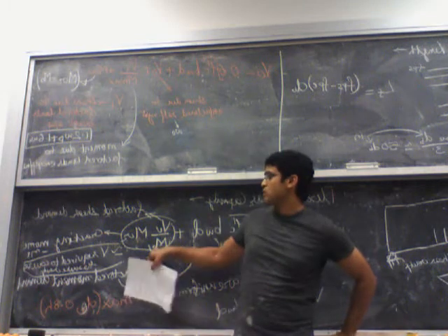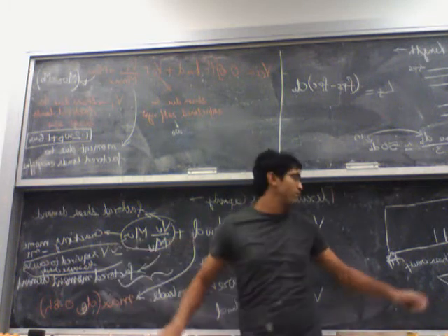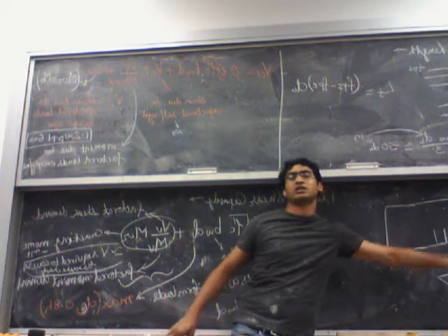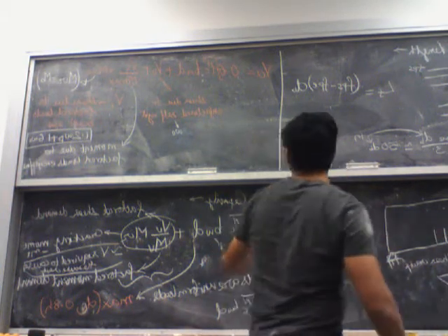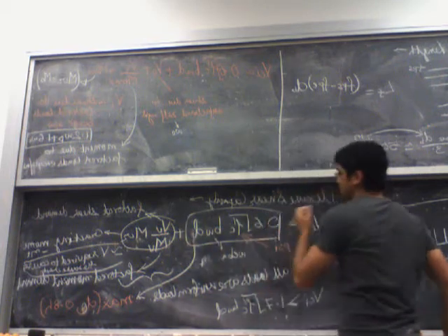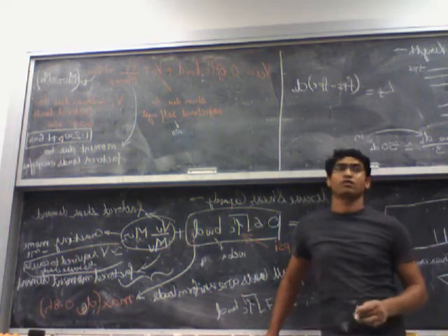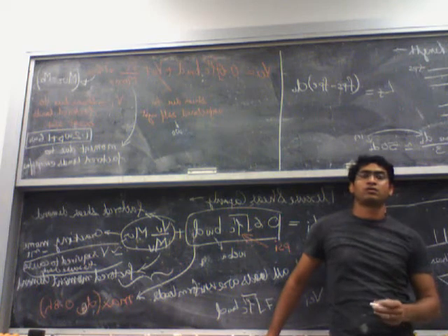This is trying to approximate the shear which will actually produce that first part of the crack, which is a flexure crack. And then the next part, which is a shear crack, is taken into account by the first term. Make sense?